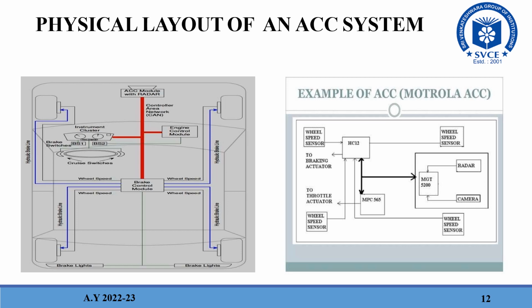Each module in the ACC connected to the CAN is called a node. All are acting as transceivers. The CAN bus carries data to and from all nodes and provides quicker control transfer to each module. The actuator used for throttle control is a solenoid actuator. The signal through the coil can push or pull the plunger.